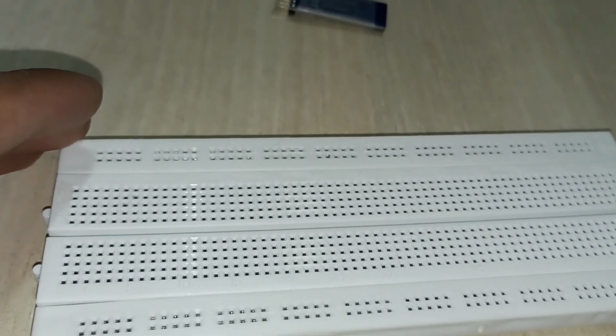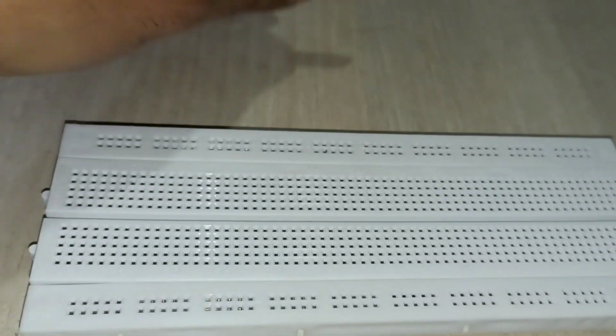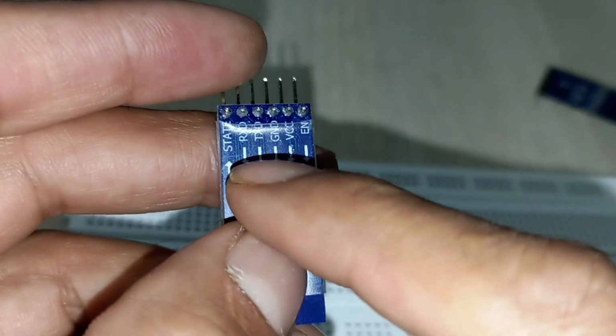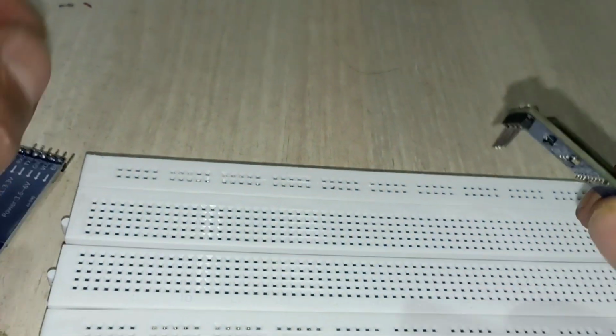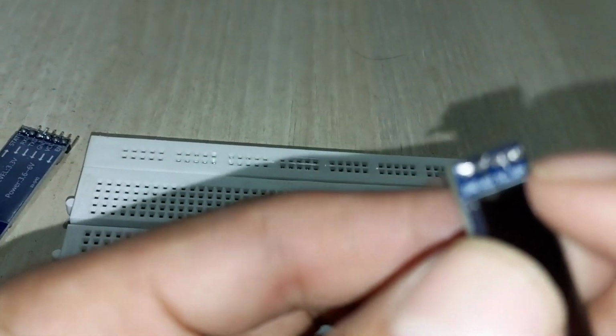communication in which we are using this Bluetooth module HC-05, and we will use this I2C OLED display. After that I will show you how UART and I2C work. The OLED works on I2C communication, and this Bluetooth works on UART communication. You can see here this is RX TX, this is UART communication, and here on the display are SCL SDA, that's